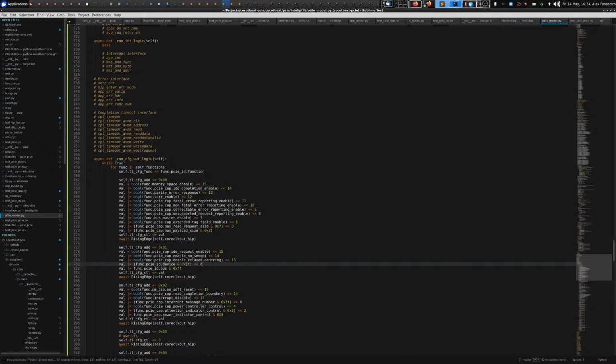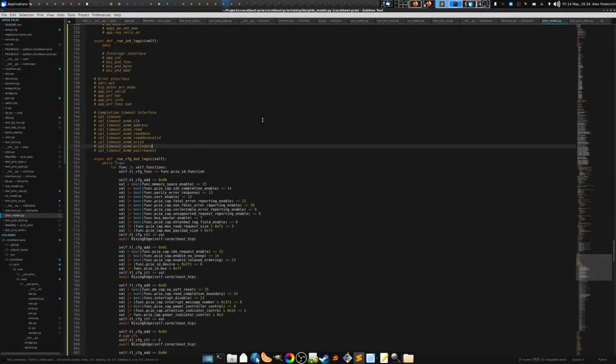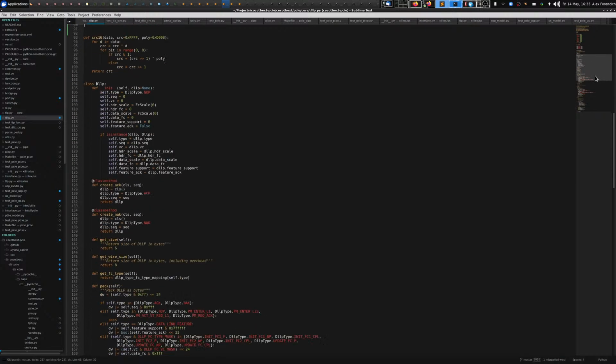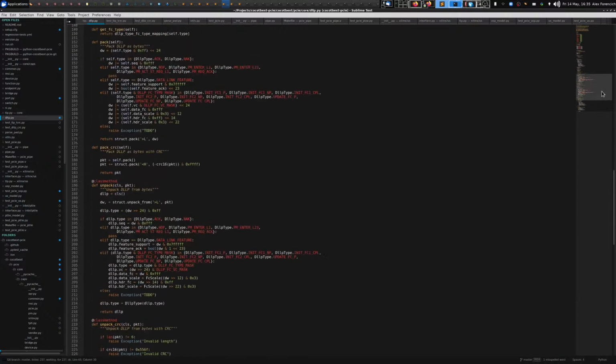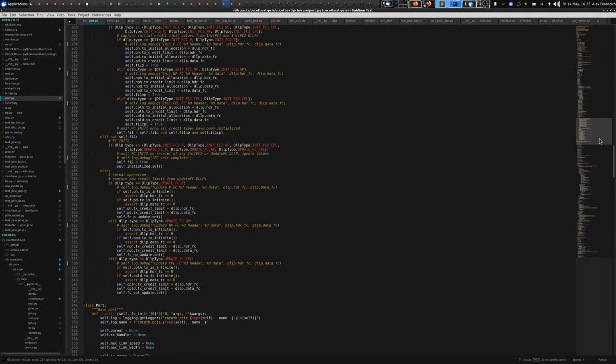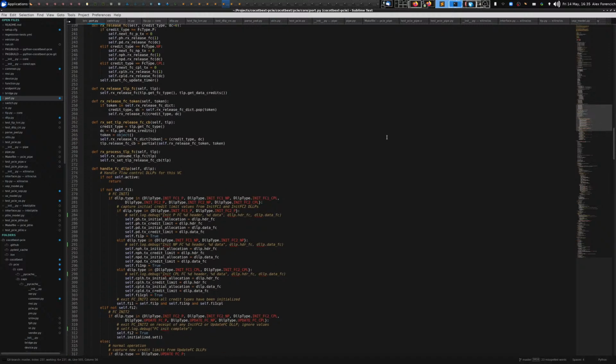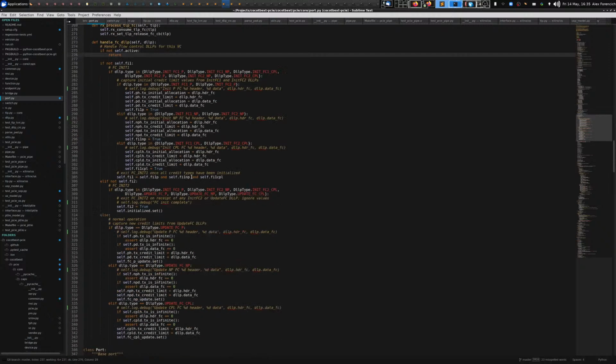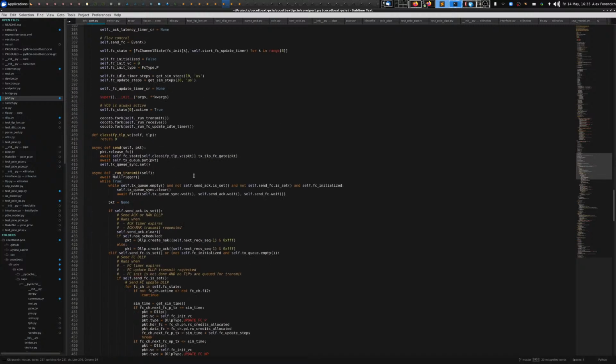Okay, anything else interesting to show here? Yeah, in terms of the PCI Express stuff, I recently made a release that included a huge list of changes, mainly covering the link layer stuff. This DLLP file I have here is only a small part of it. This is for the actual packets, but a large part of the change was all the stuff in the port module in terms of handling the DLLPs and handling the flow control as it's threaded through some of the other components.